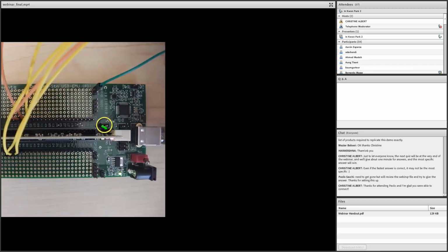In here, now we see one of the important jumpers on your control. In order to get that communication working, we need to insert this jumper at the location of J9. You can easily tell the location from this photo, or if you look at the control board, it's very easy to tell. So you may want to insert the jumper like this, or you can use a jumper wire in order to make the short connection on this jumper, and that will enable the SCI communication between your DSP and